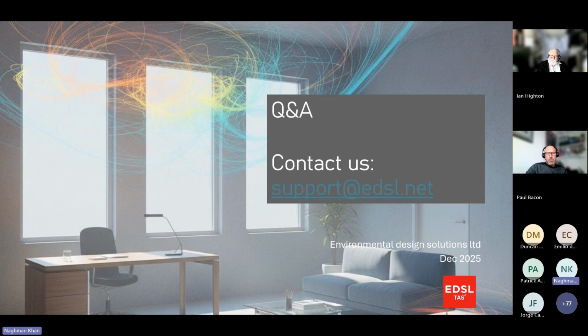Talking of problems, Alex is asking about unique shapes like a dome or an oblong dome, which I know Andrew worked on something like that as well. So how good is the CFD on shapes like that? It's absolutely fine, because basically it just fills it up like a bunch of cubes. This is the simplicity of it, and people are going to go, hang on a minute, you've got a jaggy surface running across there.